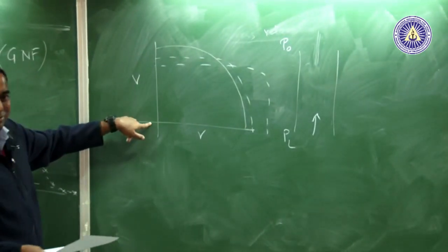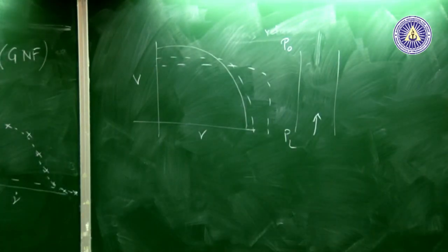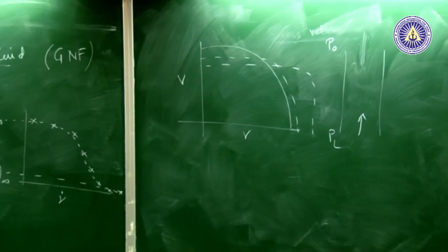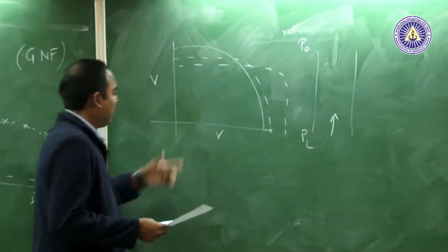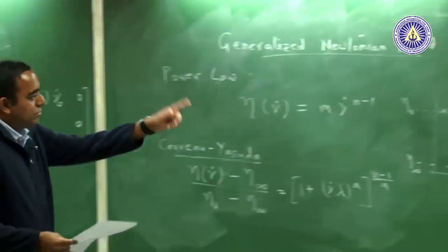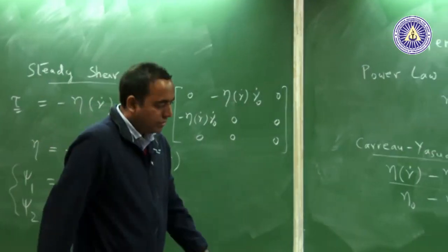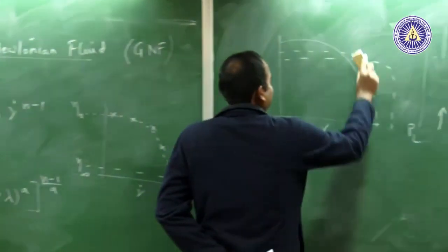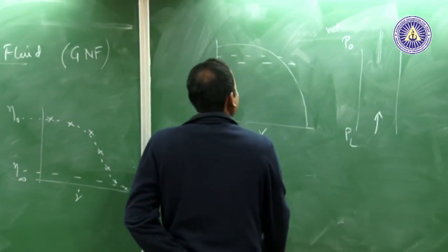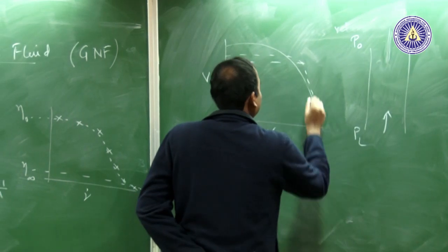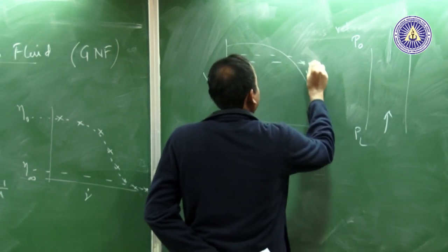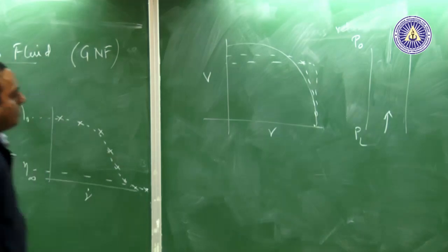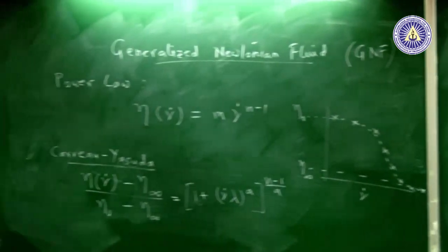This is the center, R 0. And it is symmetric about it, of course. You don't need to, it's 0 to R, that is all you have. For a flat plate, of course, you need the other side as well. They should go to 0 at the same R. That's true. Something like this, yes, because of the no slip boundary condition.